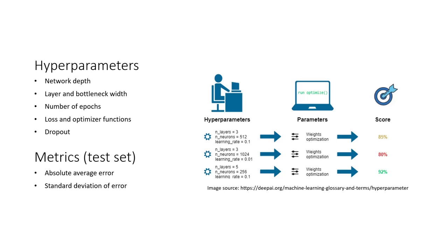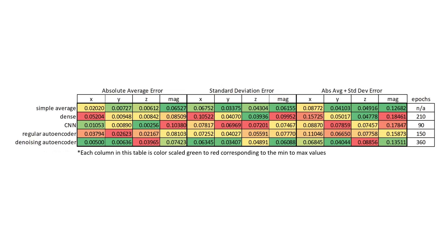The metrics used to measure success were the overall average and standard deviation of the probe-to-drogue vector errors across all 5 solutions in X, Y, Z, and vector magnitude, specifically for the test dataset. For the solutions with 36 outputs, the average was computed, resulting in a single 3-length vector. The final results for the 5 solutions are shown here.